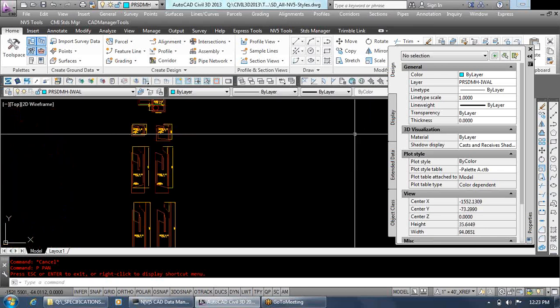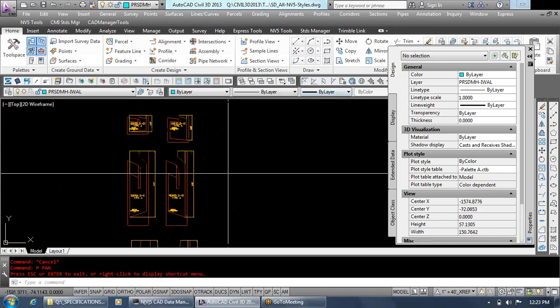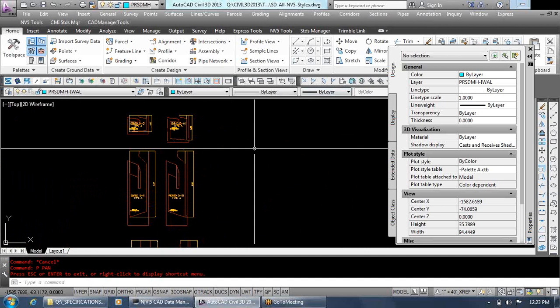All right. Just another quick note on some AutoCAD etiquette relating to your surfaces, alignments, and pipe networks. Make sure that you are naming your Civil 3D objects intelligently. Sometimes, the standard convention here at NV5 for a proposed surface is just PO1. However, that PO1, what is it for? What is it to? Having just a PO1 doesn't really describe it enough.